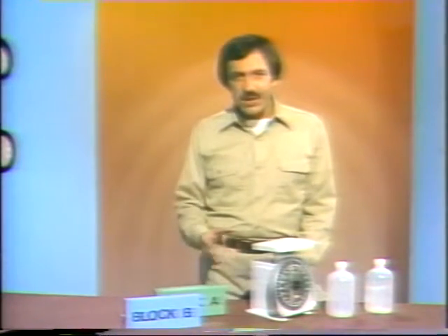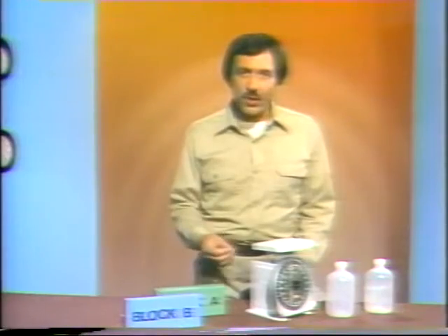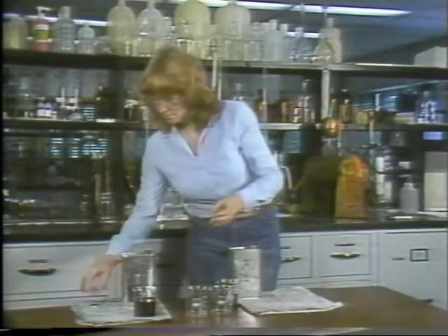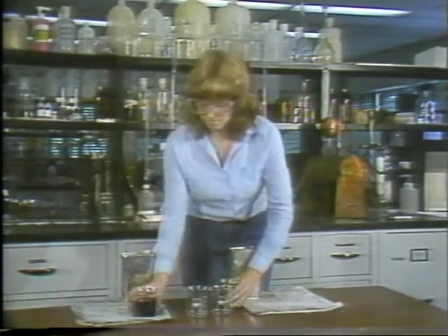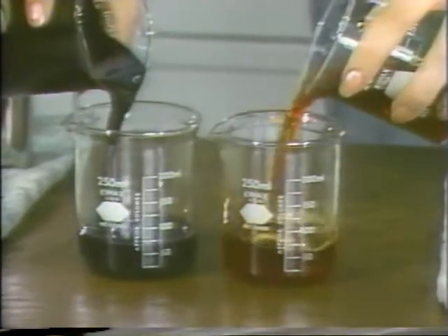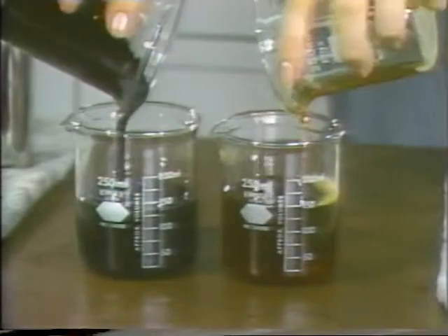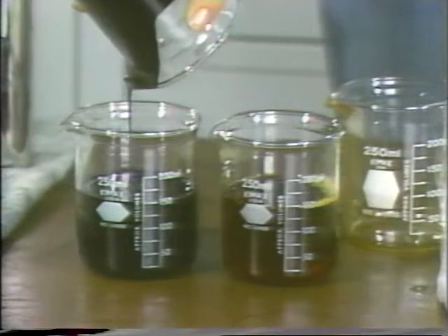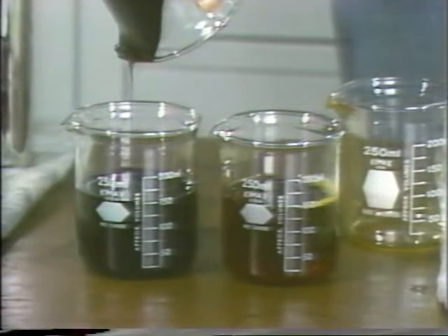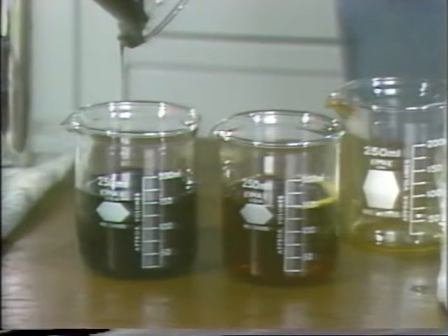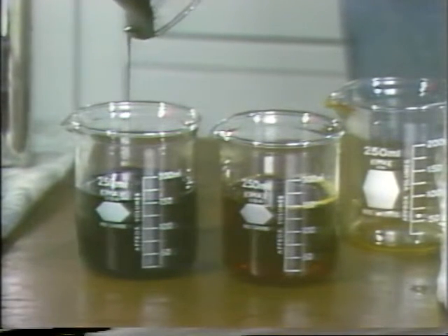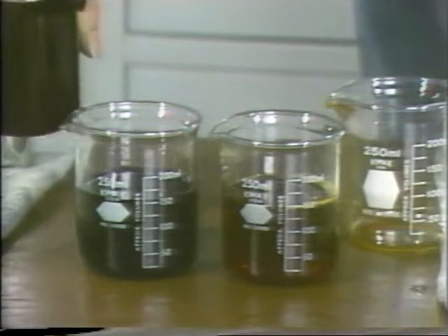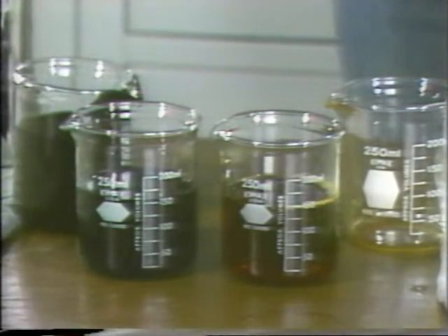Viscosity, which is the measure of a fluid's internal resistance to flow, is most often associated with lubricants. In the lab, we can easily demonstrate the property of viscosity by comparing two different lubricants as they're poured. The lubricant on the right has a low viscosity. It is thin and flows quickly from the beaker. However, the lubricant on the left is thicker and flows much slower. It has a higher viscosity. Therefore, we can say it has a greater internal resistance to flow than the lubricant on the right. This is evident by the additional length of time it takes for the lubricant to flow from the beaker.